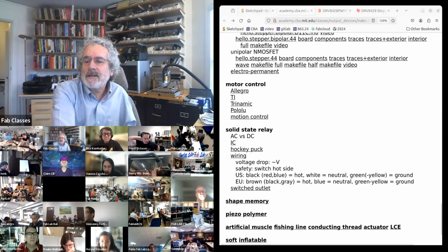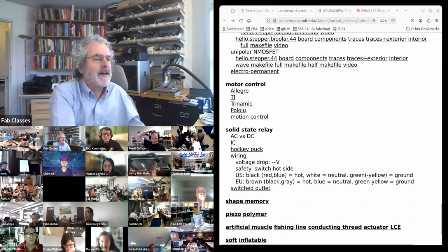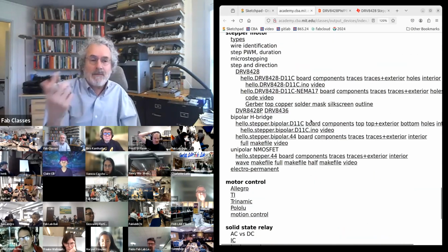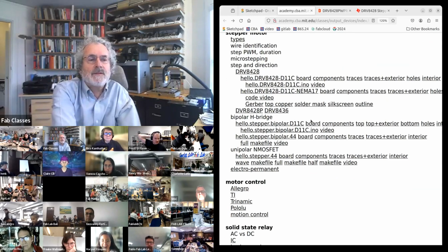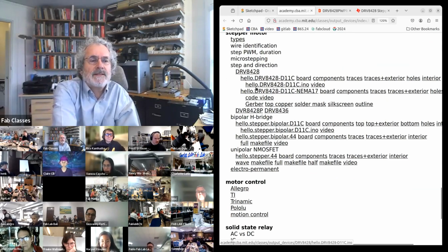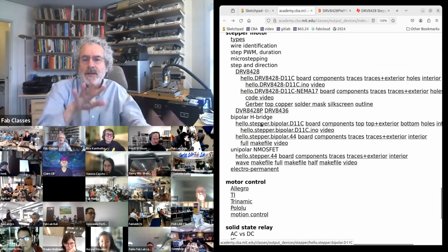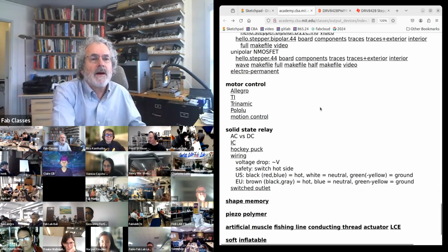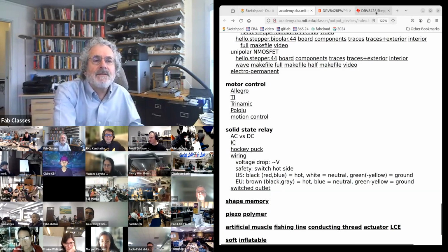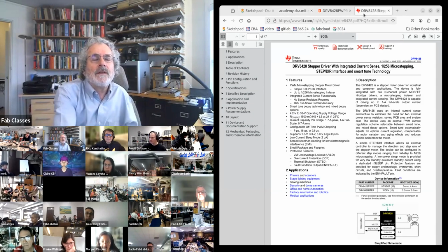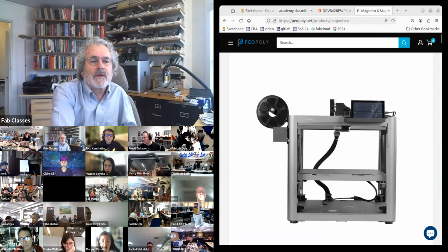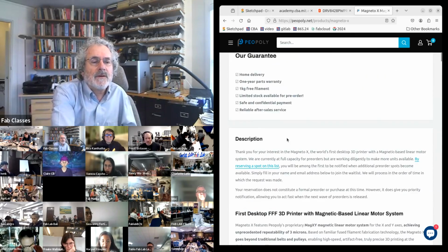Oh, yeah. There's a link in the chat that's very important that I missed, that I'll explain. The quiet steppers, those are nice, but you can do it in software. So with the microstepping on this and with microstepping on this, you can implement quiet steppers on any of these as long as you can microstep. The link in the chat is one that I should have linked.